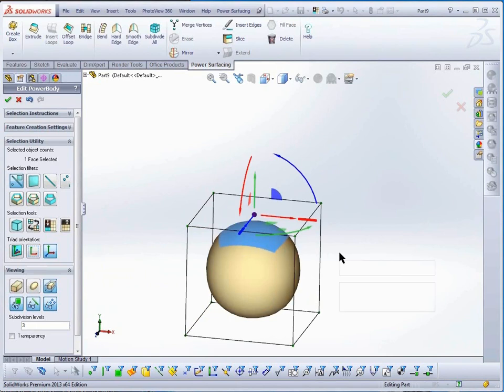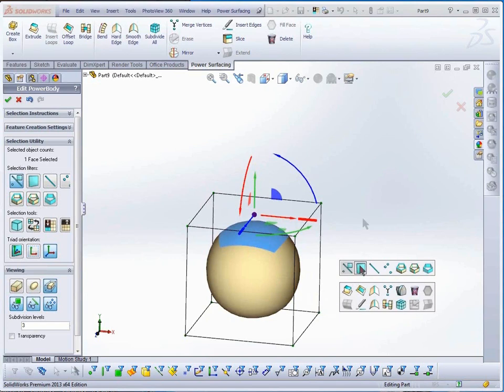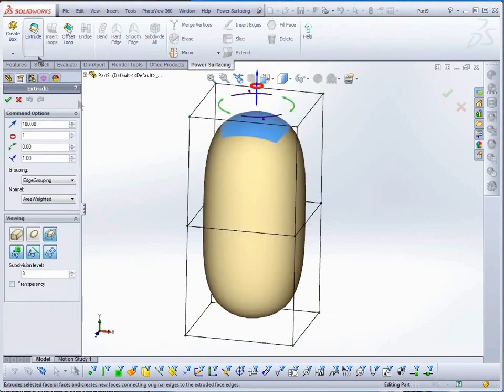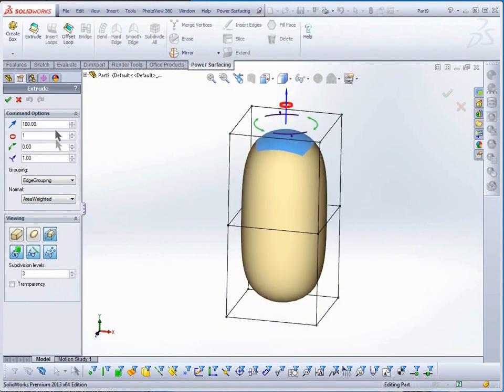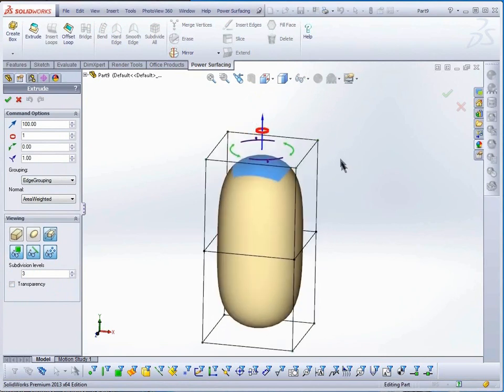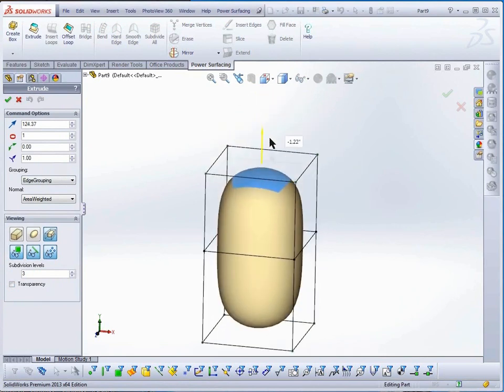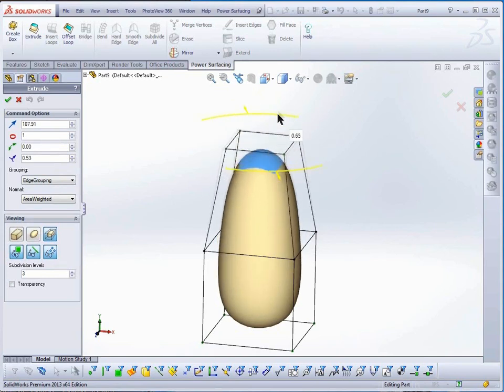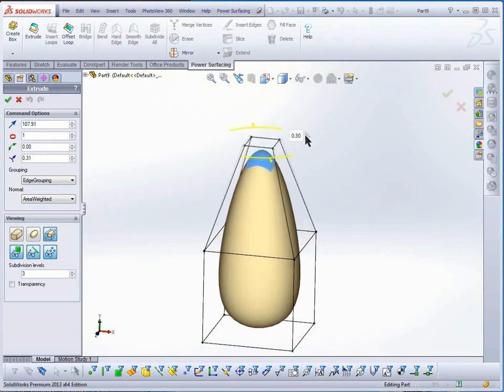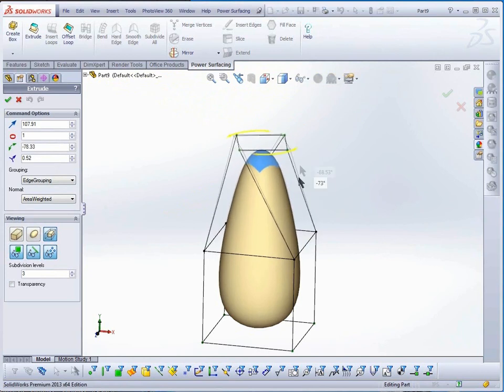Select a face on the mesh. Choose Extrude from the right-click menu or from the toolbar. The face is extruded out, and the Extrude parameters are shown in the Command Options rollout over in the Command panel. You will also notice that the context-sensitive gizmo has changed to reflect the new options. With Extrude, you can adjust the extrude distance with the Distance gizmo, scale the extruded face with the blue Expand gizmo, and rotate the face with the green Rotate gizmo.